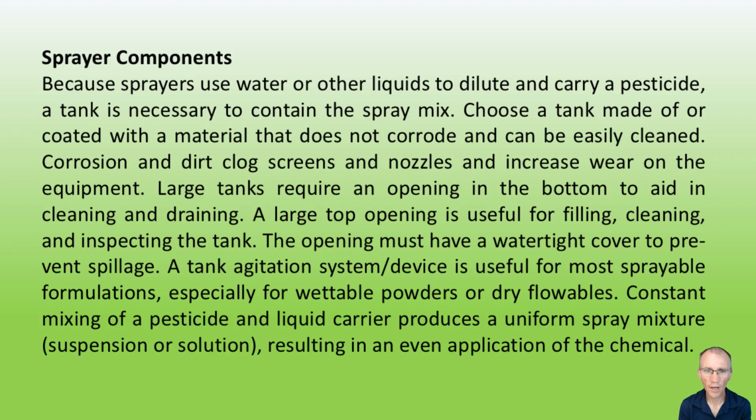Because sprayers use water or other liquids to dilute and carry a pesticide, a tank is necessary to contain the spray mix. Choose a tank made of or coated with a material that does not corrode and can be easily cleaned. Corrosion and dirt clog screens and nozzles and increase wear on the equipment. Large tanks require an opening in the bottom to aid in cleaning and draining. A large top opening is useful for filling, cleaning, and inspecting the tank. The opening must have a watertight cover to prevent spillage.